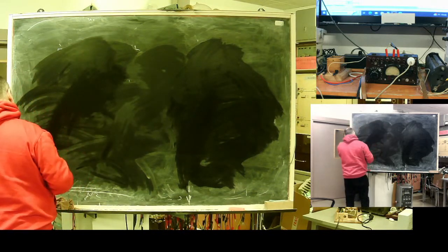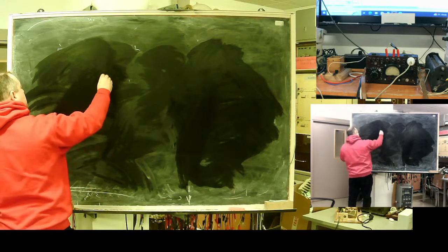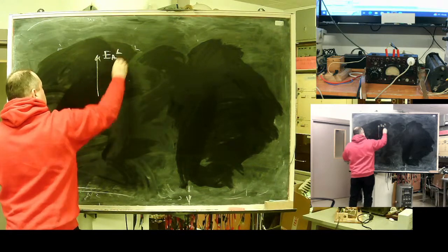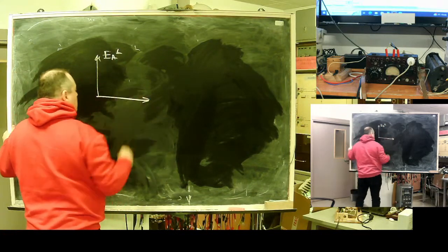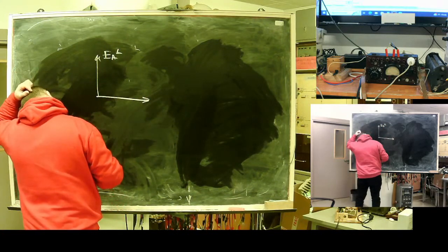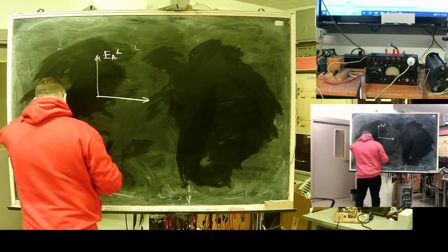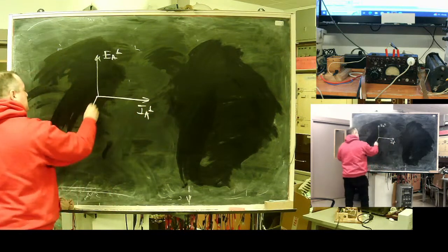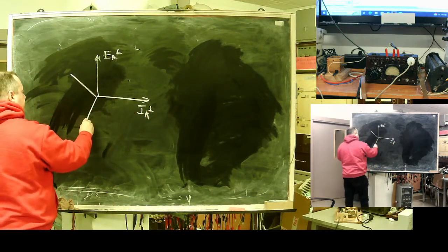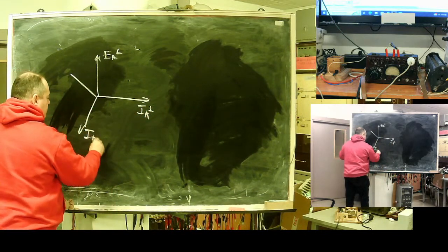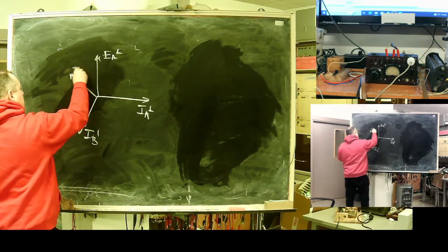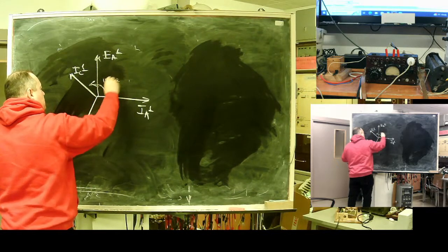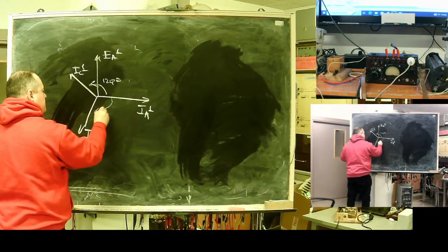I will see at the fault side something like this. It will be a phase sequence with an ideal transformer at 90 degrees. I will have the A direct sequence, B phase direct sequence, and C phase direct sequence, obtained with a 120-degree shift.